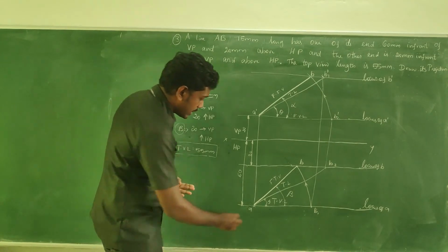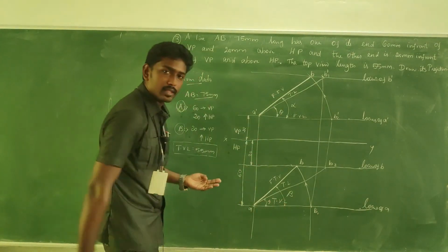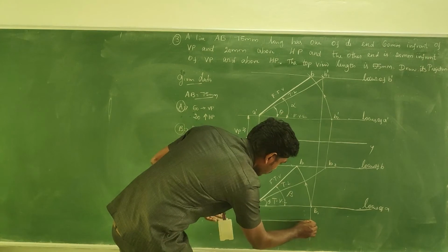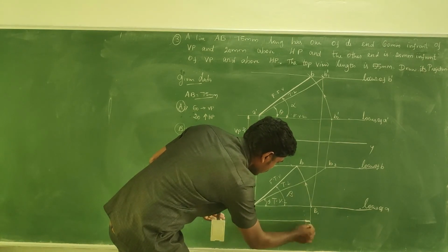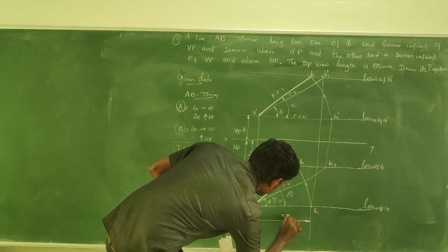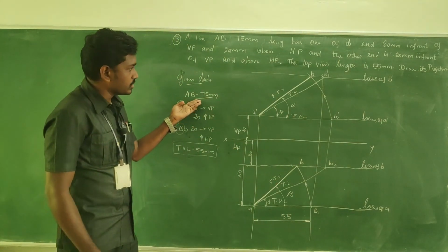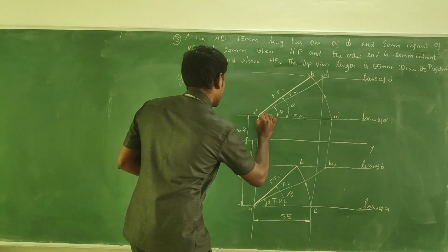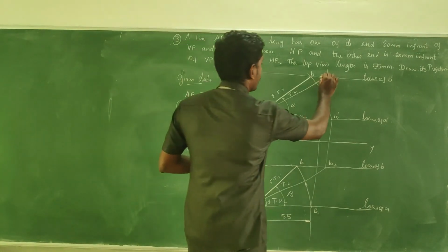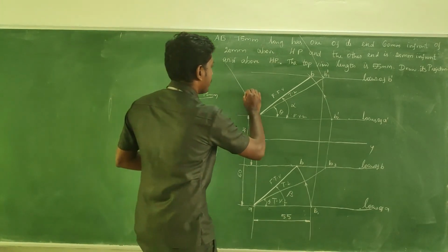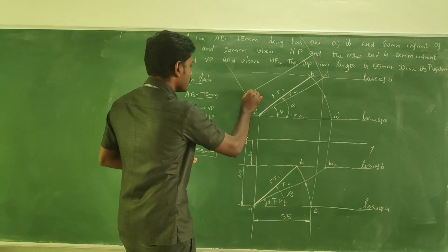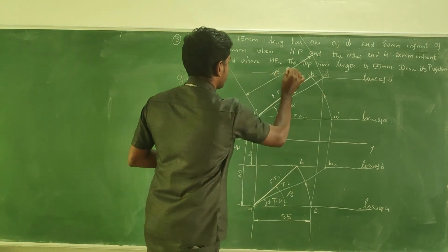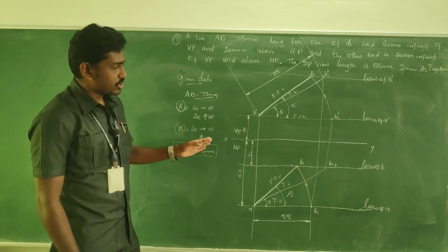The top view length is there, that also should be specified. Here is the top view length. So take the dimension line like this, make filled arrows on both ends and write the measurement 55. True length is there, right? Where we can capture it, I am going to prefer the front view. So take the extension line from both the ends, something like this, go for a line parallel to the true length, capture the filled arrows and right above it write 75 mm. The dimension work is over.